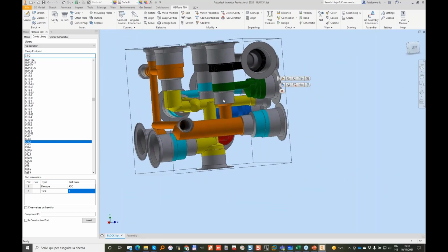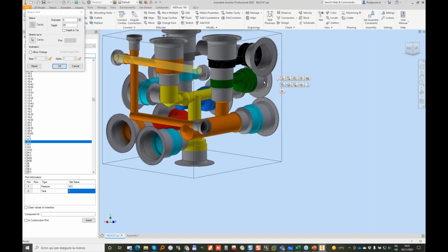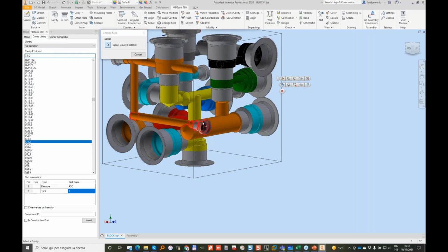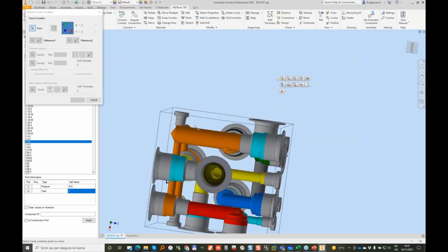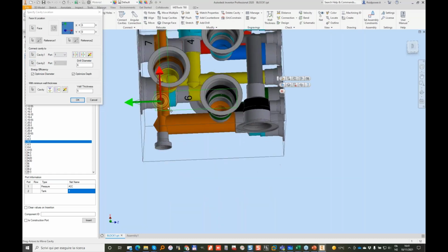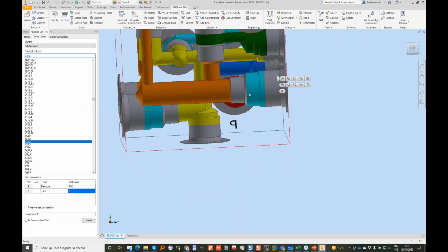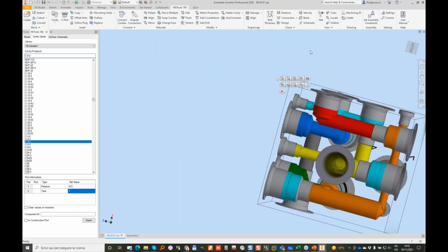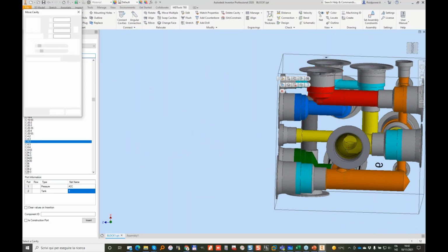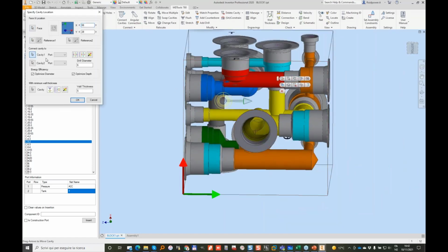Now that I have made this trick, I can really say stretch this drill up and change phase to this plug and put maybe on the top face and connect here and here. And now I have room for a plug here and go back to the tank line, which is on this position. I'll move my P port and I copy my construction plug here and connect.